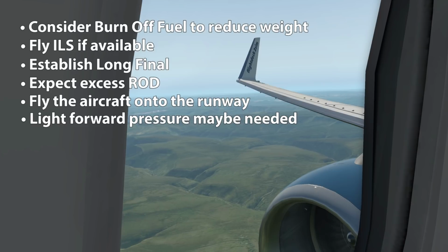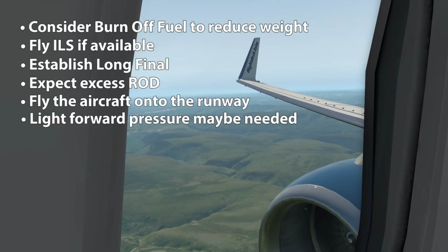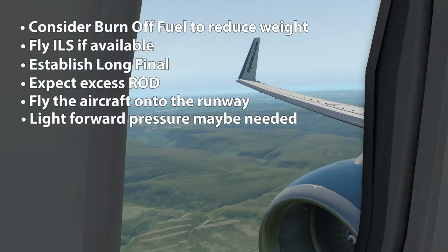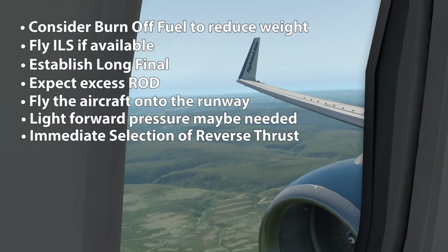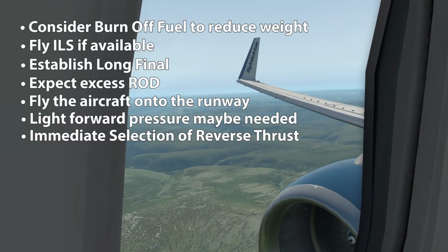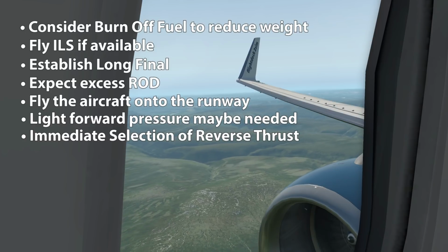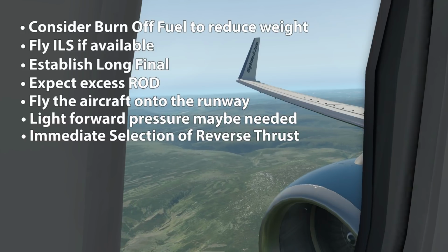After landing, we just want to hold very light forward pressure just to ensure that the aircraft doesn't want to get back into the air again. You might even during the flare have to put the nose down as well to get it into the touchdown zone. And then as soon as you've touched down, you must immediately select reverse thrust, to reduce braking pressure to the absolute minimum required to avoid excessive brake temperatures. So we're going to use max reverse thrust, obviously the speed brake, and as soon as stopping's assured, we'll disengage the auto brake and use all the runway available to come to a safe stop.